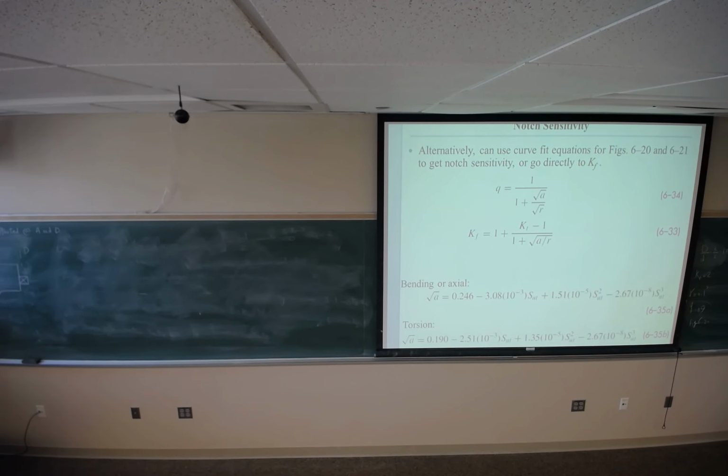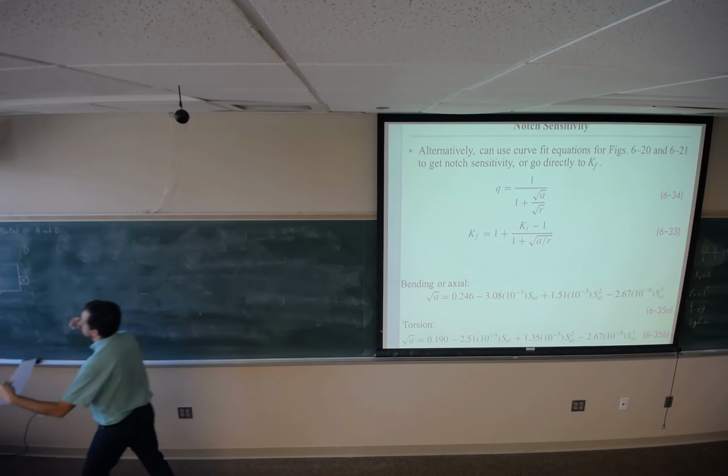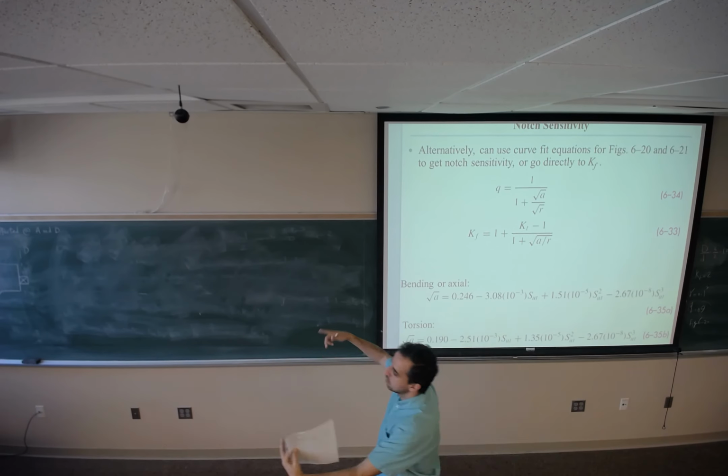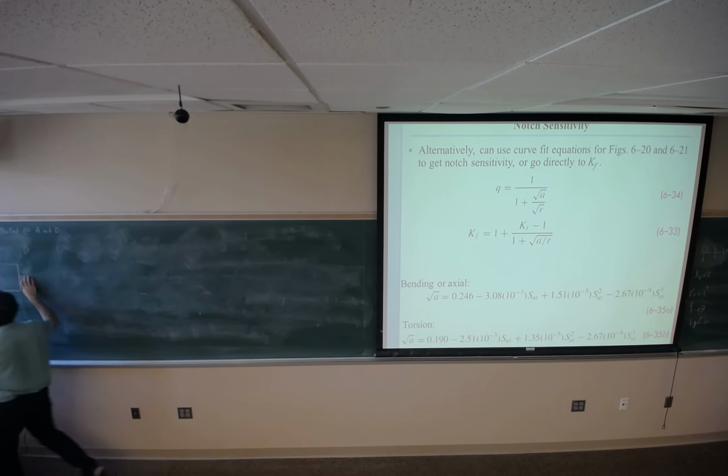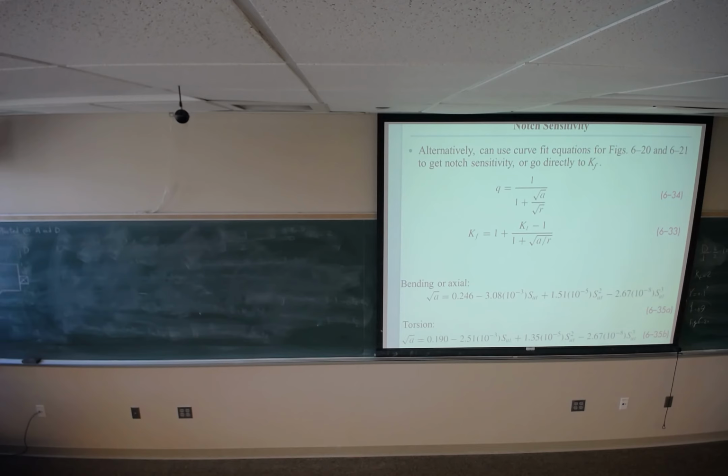It has a smaller diameter, a larger diameter, and another, the last part, which is going to be this part, mounted on these two ball bearings. So these two ball bearings are going to support the shaft while it's rotating. So it's mounted on this ball bearing. They represented the ball bearing. It's simply supported. Just imagine it like this. They are rotating about these two bearings.